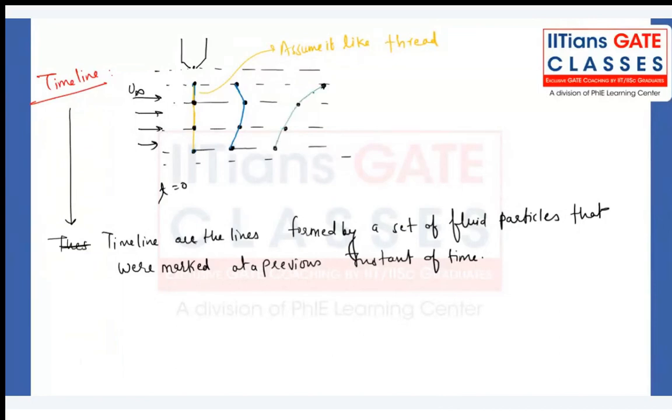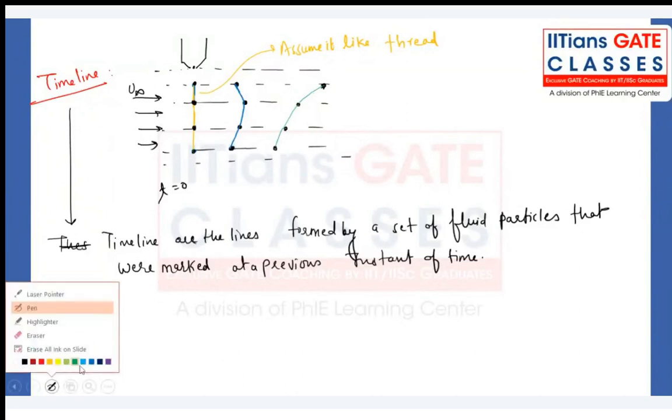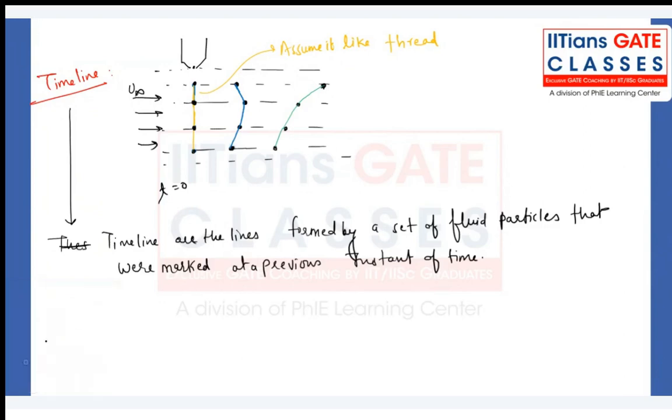So what we are observing is, which kind of flow field is it, because you can see that some deformations are happening, right? The fluid particles initially were straight, but now they are deforming, right? Something is there that is rotating the fluid particles. What is that? Rotational flow field. It is a rotational flow field, right? That's why the thread is basically bending or taking a curved shape.